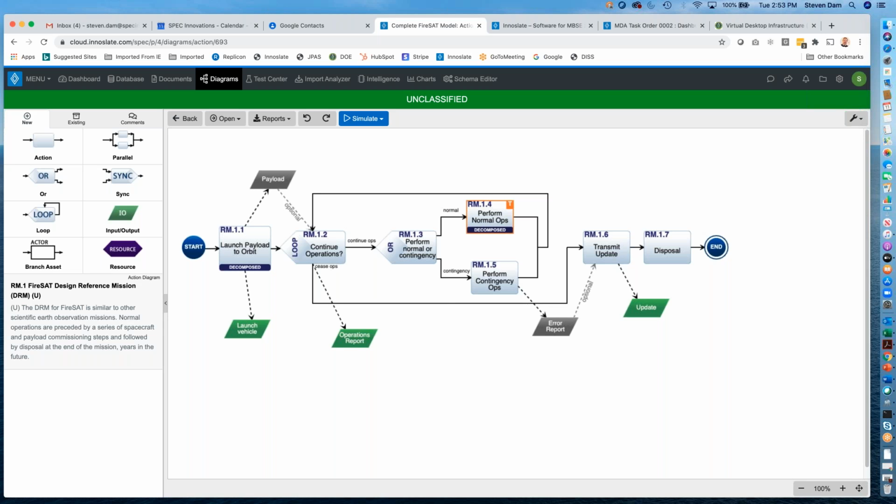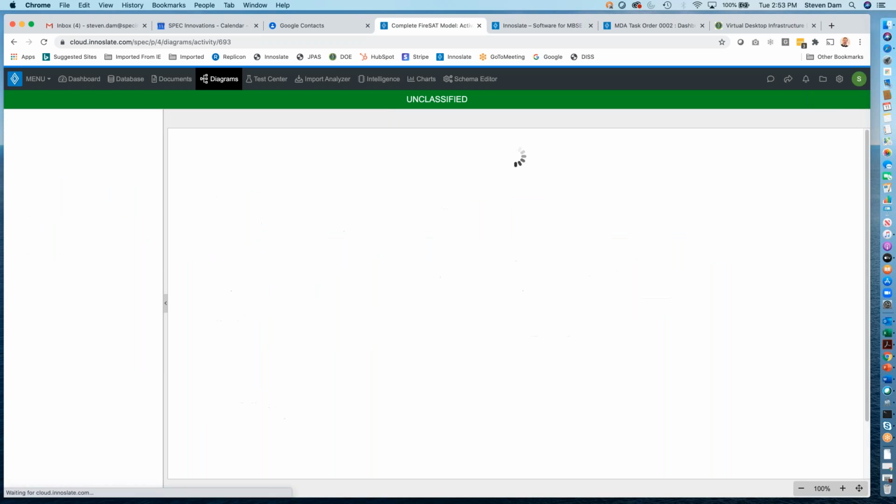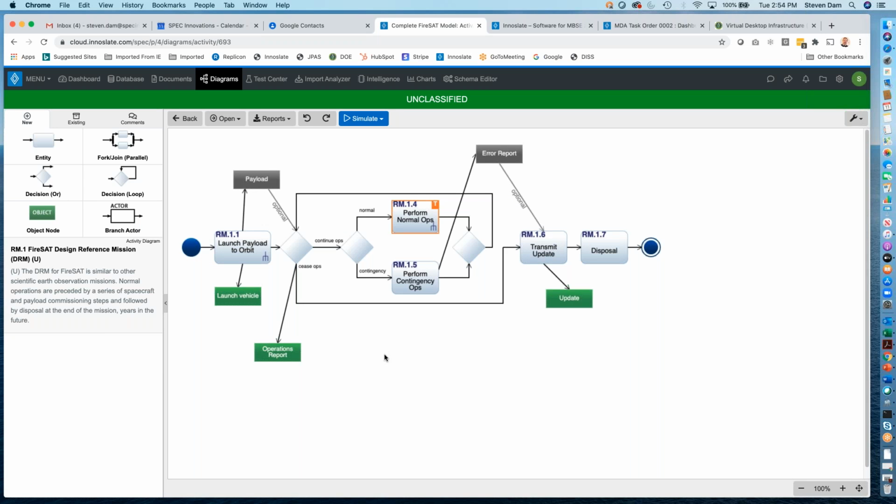Thank you. I didn't follow how LML lets you have the auto generation. What was that word again you used that MBSE needed? Can you explain that a little more? Yeah, concordance. So concordance is that thing about moving from one diagram type to another with the same data. So I'm not drawing these other diagrams. From here, when I select activity diagram, it just reads the database, looks at the same data, and portrays it in this format, because that's the standard format for the activity diagram. So those are the things that it's doing automatically.